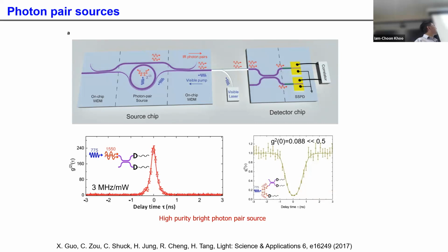Yeah, that's just a different wavelength, because the reason you see the waveguide coupling to the resonator is different for each wave. Because the shorter wavelengths have better coupling, you need to make them closer. And you also want to make it strongly coupled, so you want to make the interaction longer. It's just different wavelengths. See, that's a design factor.